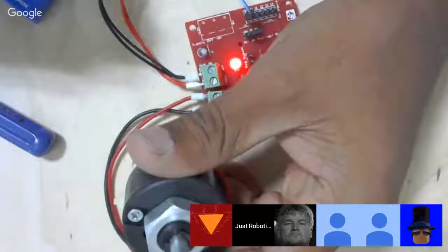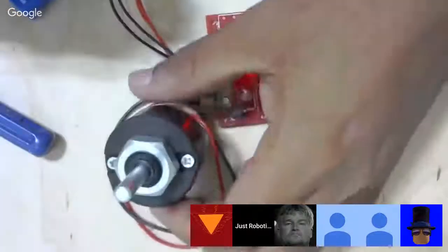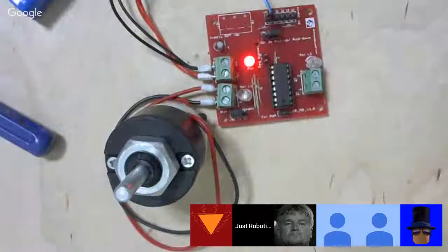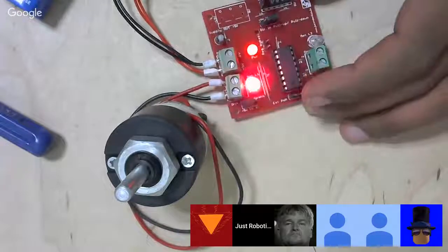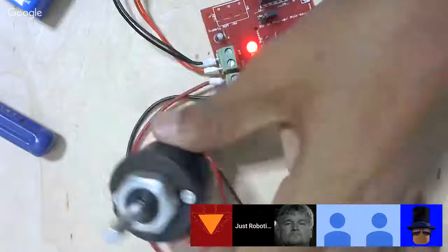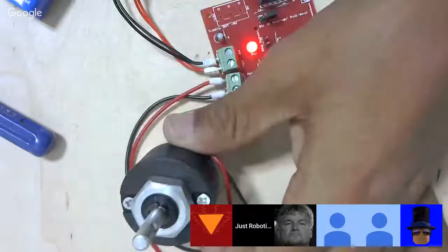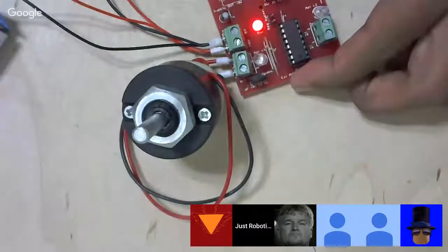This can only be done by what we call pulse width modulation. Now don't get worried about the terms, but if you actually look at what pulse width modulation is, it's very simple. This motor is rotating at a particular RPM, can you see that? Yeah. Now what I do is, instead of having the motor rotate continuously, I will just do this.